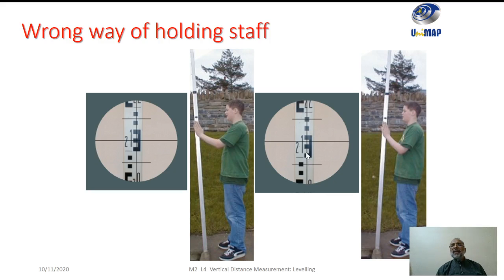This vertical hair can be referred to in order to decide the verticality of the staff. The staff should not be tilted away from the body or towards the body, but it should be held exactly in the erect manner.